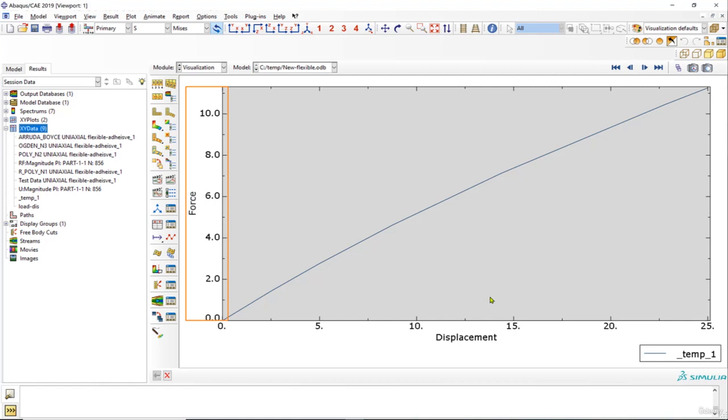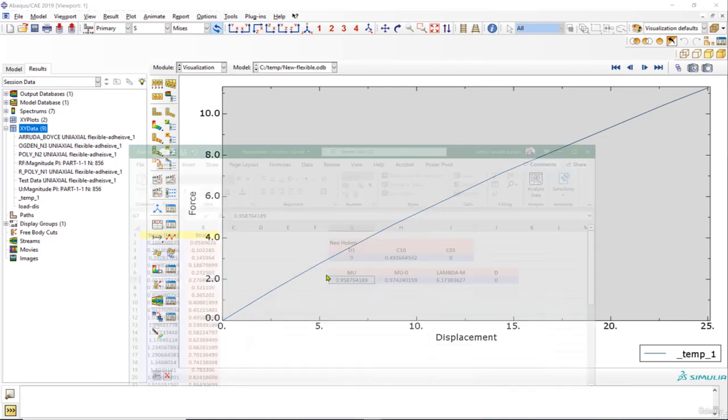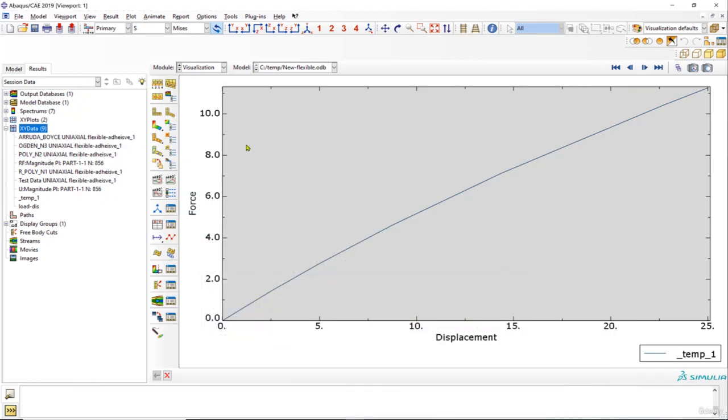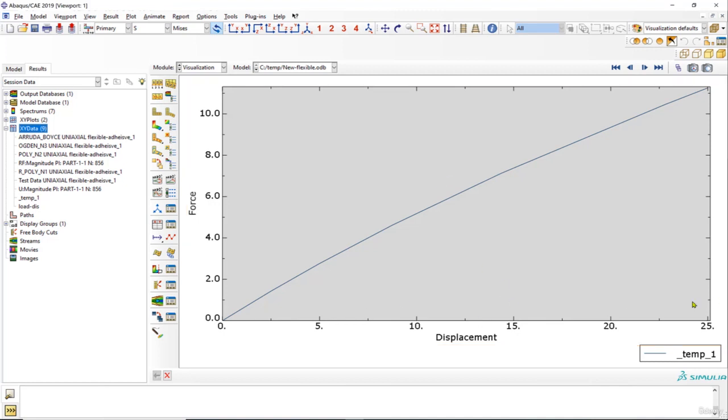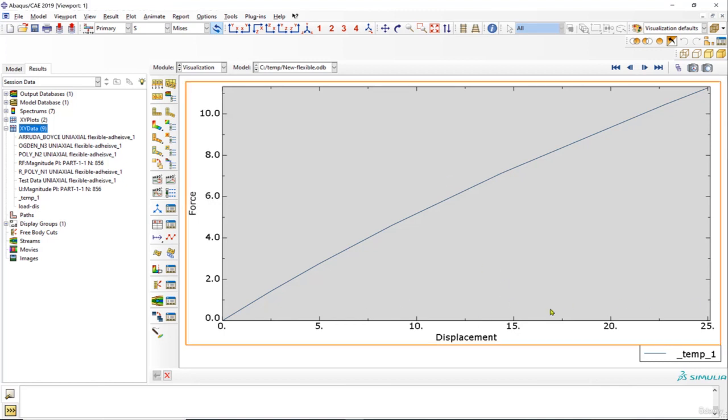force displacement, so you cannot actually compare this one with the stress strain data that we had in the Excel file. This result that you get, you have to compare with the experimental data that you get from a tensile test machine, and if you are using any sort of non-contact measurement to measure displacement, or even you can use the crosshead data, because the displacement is quite large, so slipping is not going to really affect the result that much.